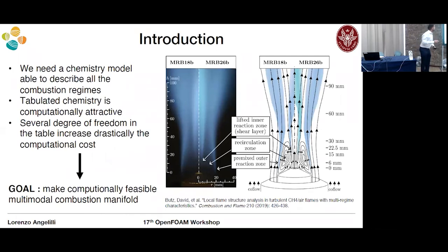In order to simulate combustion, the normal continuity equation is not enough, because we need to introduce the effect of the different species. So we need a number of equations to transport the species mass fractions, which depend on the number of species in our chemical kinetic mechanism.